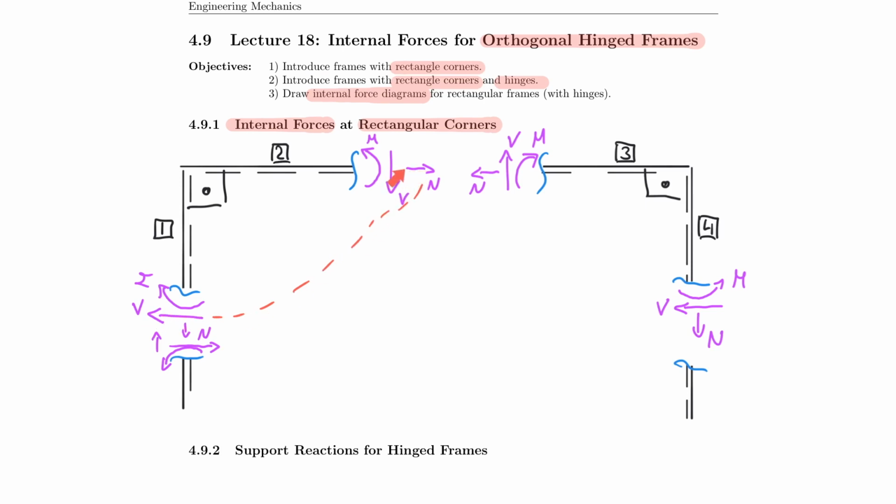So whatever force the normal force takes up here has to be balanced by the shear force in the corner. And I want to point out again, this corner can be as tiny as a millimeter only here, and this picture would still be true. And in that case, the normal force has to balance the shear force at that corner. But this is only true because we're dealing with a 90-degree corner.